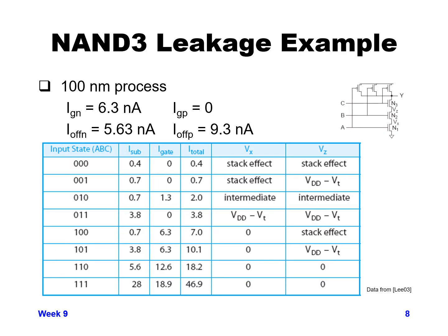So this foil goes through an example for a NAND 3 and talks about leakage, comparing subthreshold leakage and gate leakage in order to get total leakage, depending on the value of your inputs. There's a lot of information in this foil, and I'm not going to talk through all of it.